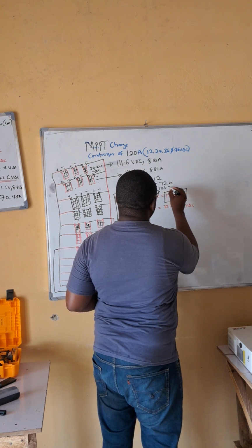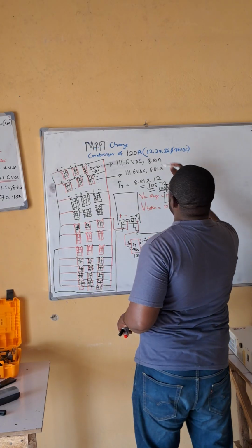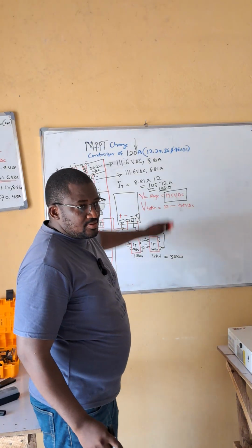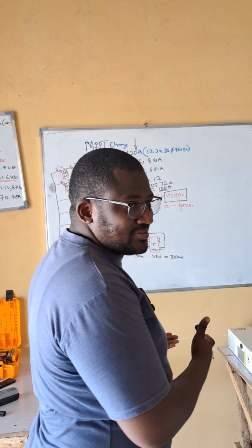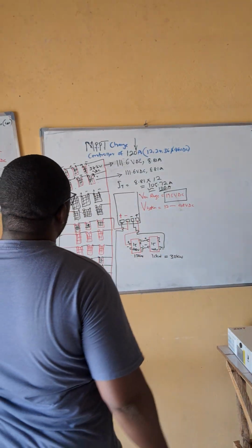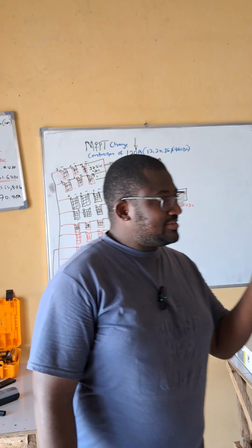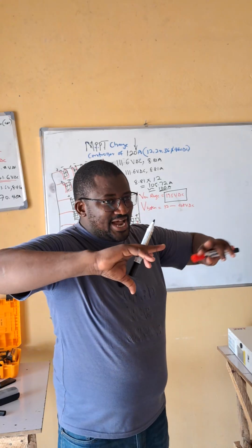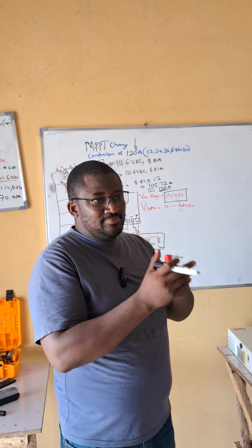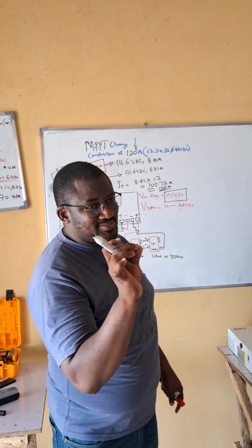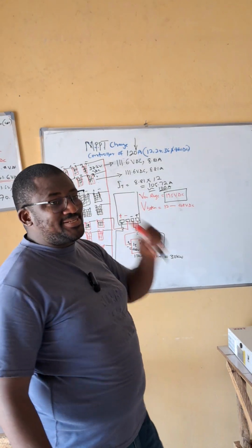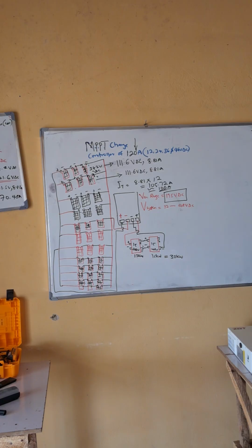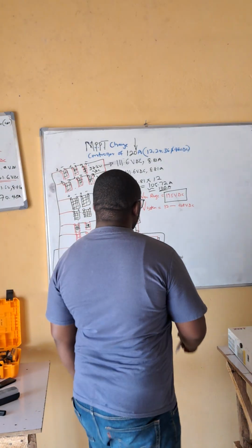Approximately 106 amps. Meanwhile, we are dealing with which type of charge controller? 120 amps, which means it can accommodate this current conveniently. We still have a space. So this is it. If you can remember, when we deal with PWM charge controller, we have to get 2 charge controllers and cascade them together to give us 160 amps for it to power only 24 panels. But here, we use 36 panels using only 1 charge controller, and all is well. So what is remaining now?